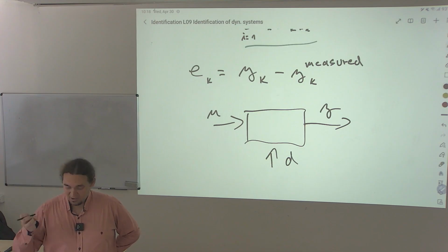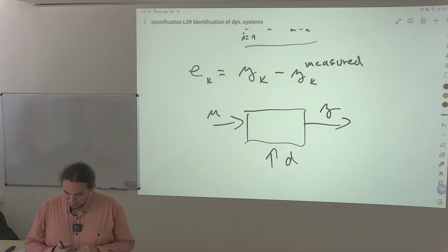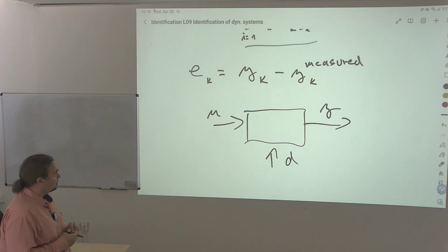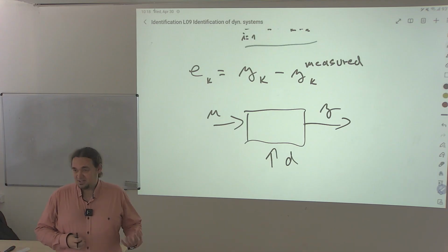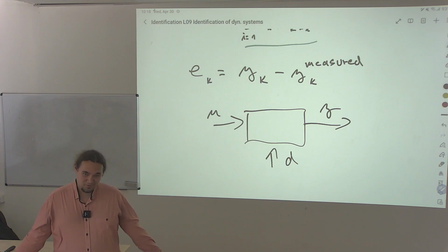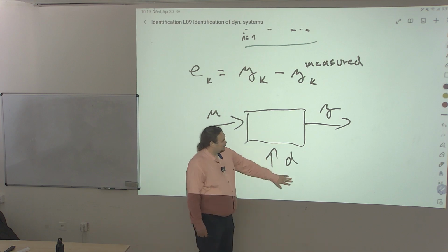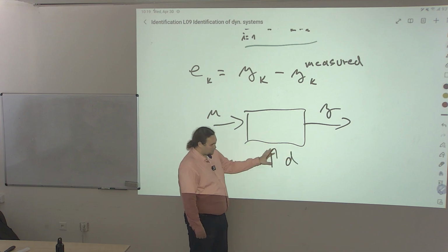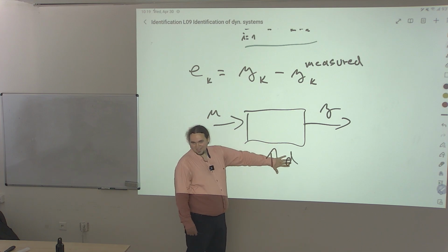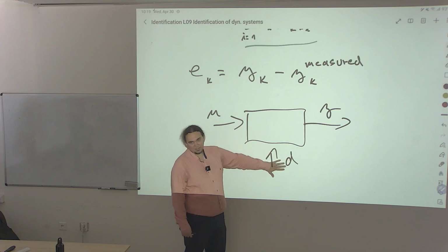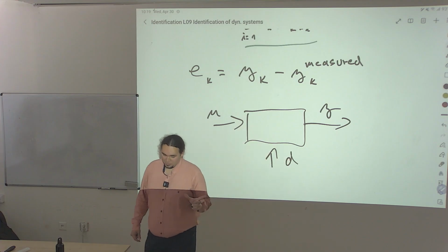So, for example, a leaking valve would be a good example of a disturbance, and this disturbance can, of course, happen in the historical data. So actually, when training the ARX or FIR models, we are completely neglecting the fact that there is some disturbance.